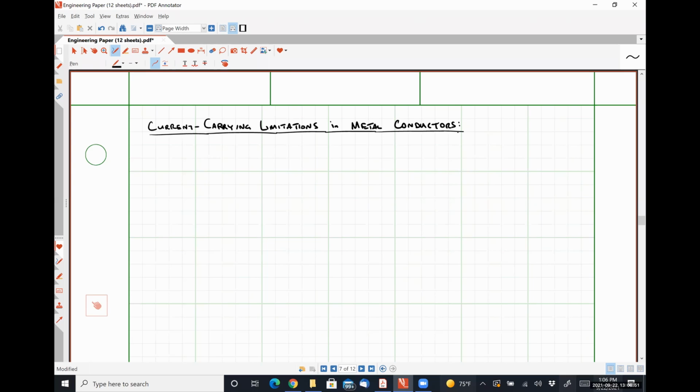How many of you are familiar with the concept of ampacity? Thoughts on what ampacity is whatsoever? Okay, most people are shaking their heads. That's perfectly reasonable. So ampacity is a wire's ability to carry current without heating up so much that it melts the insulation that's holding it, right?